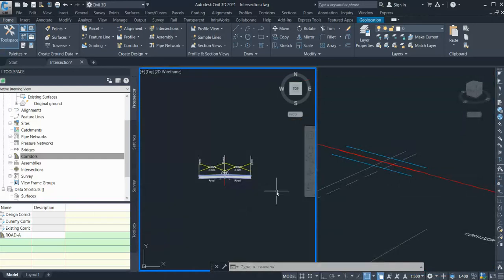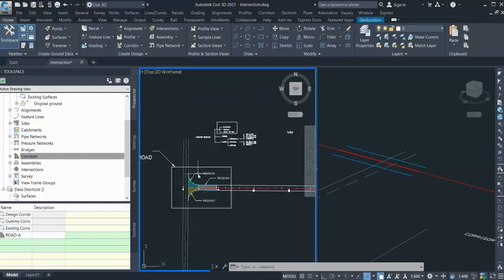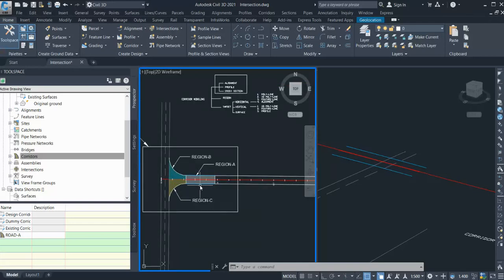So this is also one of the points I can tell from experience. Whenever you're designing any corridor, always start with the lanes only. So first you create all lanes, create the alignment, profile, and everything finalized. Then you start modeling into detail.